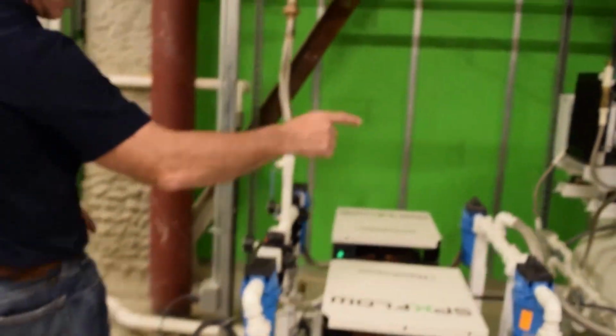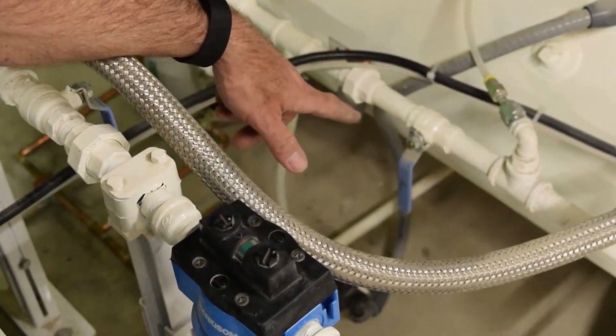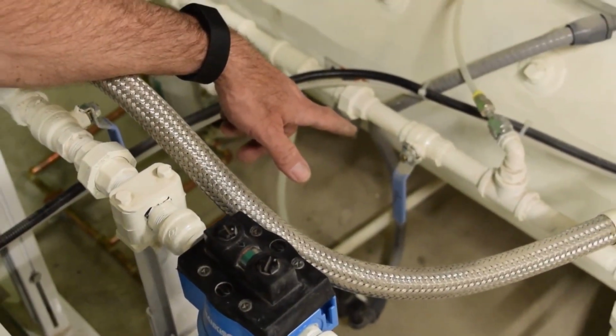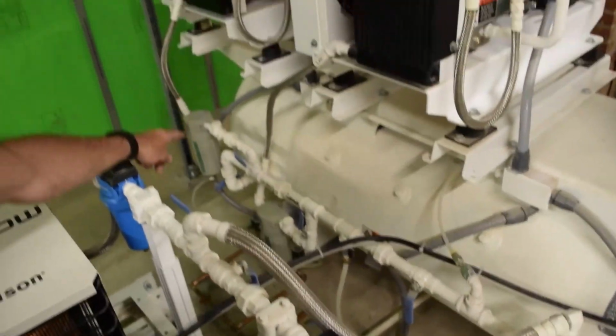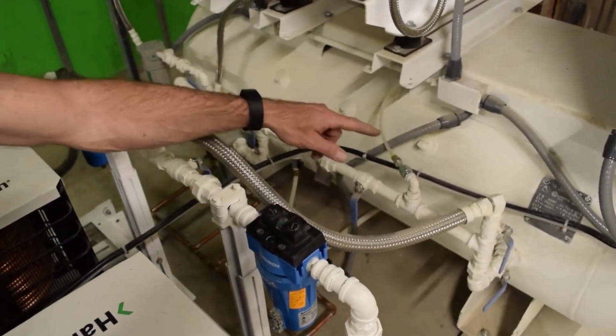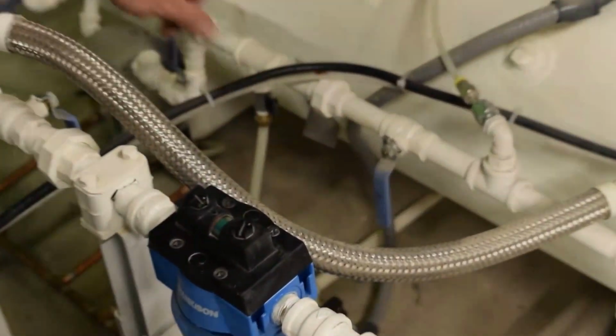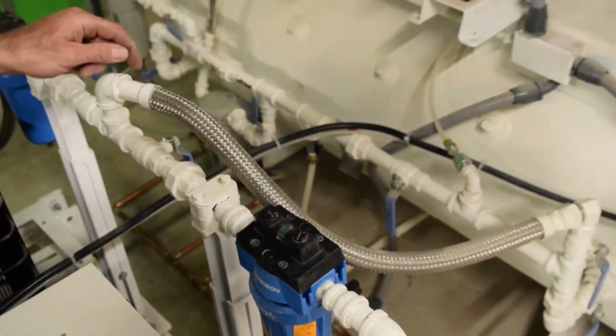So if you look at the valves on the tank side here, just focus in on those if you could. You'll notice this valve is off. That valve should always stay off. That's your bypass valve. The air has to go in on this side of the tank and come out on this side of the tank, making the receiver tank trap any moisture and get rid of it. If this valve were open, you would pass the hot wet air right into the dryer.